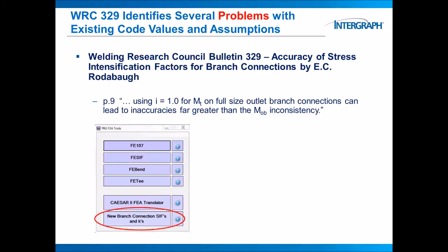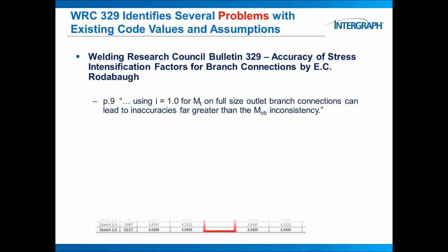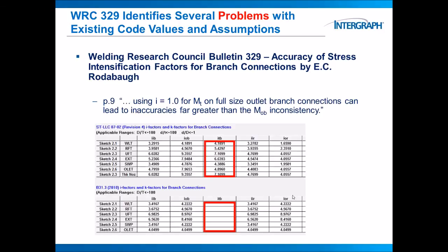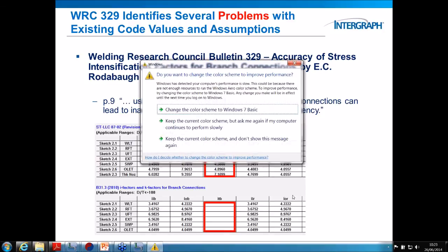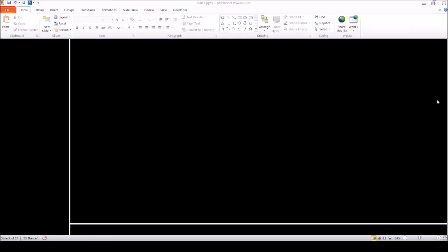And here's an example, and we'll just take a brief look at one of the other modules of FEA Tools, the IK calculator, where you can input T geometry and you can get an instant idea of what the stress intensification and flexibility factors would be, automatically.